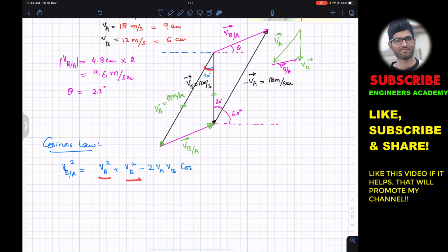So the included angle is 30, so cos of 30. And now if we want to find VBA magnitude, we need to take the square root on both sides of the equation. So now VA is 18, VB is 12, minus 2 into 18 into 12 cos of 30 under the square root.